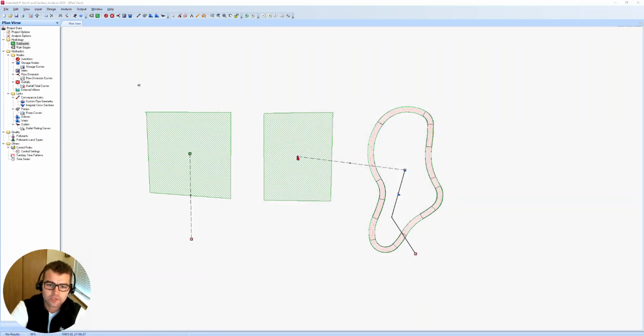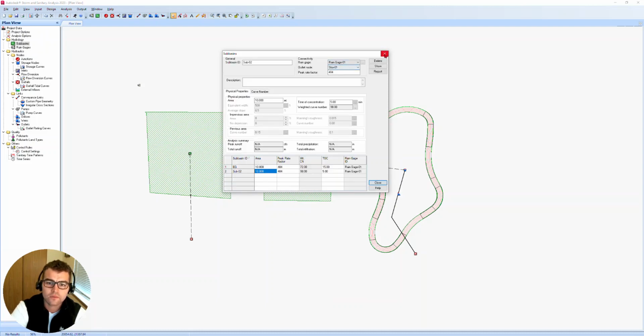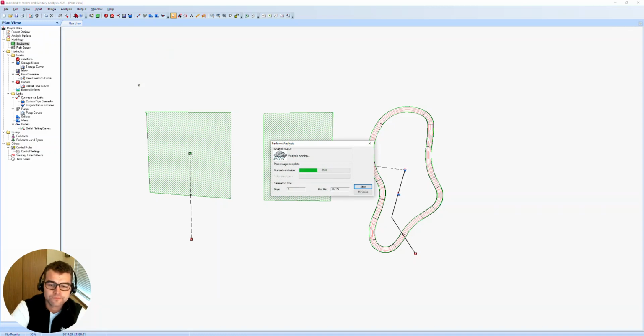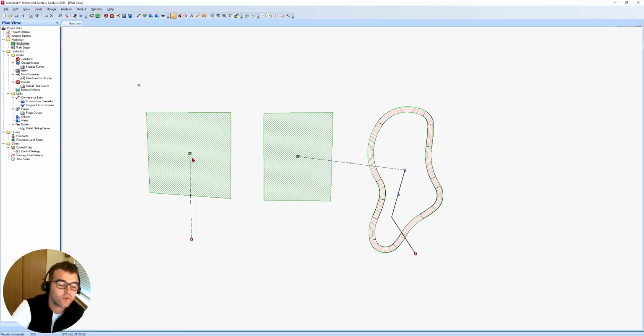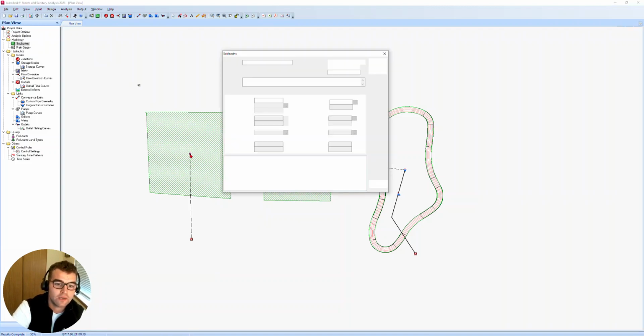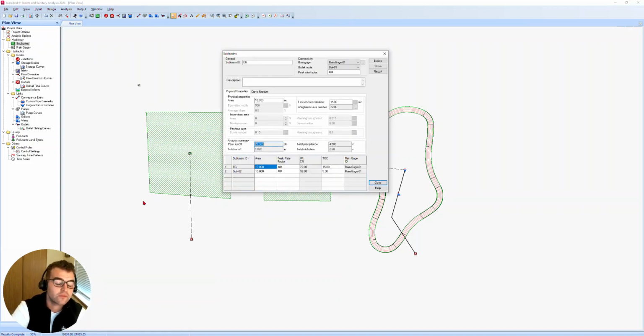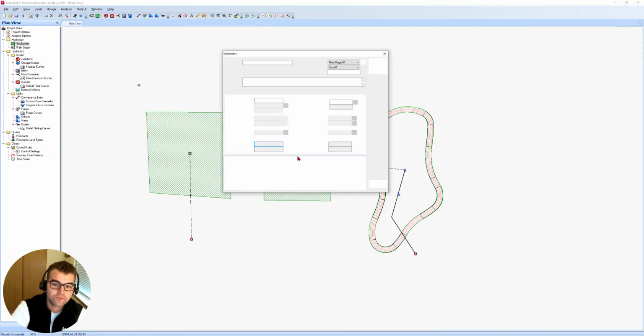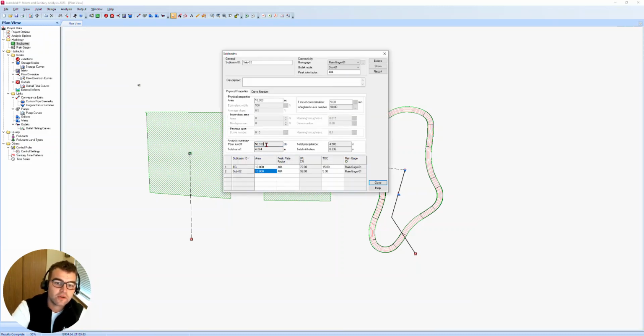And let's just double check my subbasin here. Storage node, yep, okay. All right, let's go ahead and run this now. We're running our model now. And so we're running this simultaneously on both sides. So just keep in mind when we run it, there's our peak runoff on our EG. Now let's see what's going on in our proposed conditions. Okay, so peak runoff, 58 CFS, so about 3 times more flow coming off in this scenario.